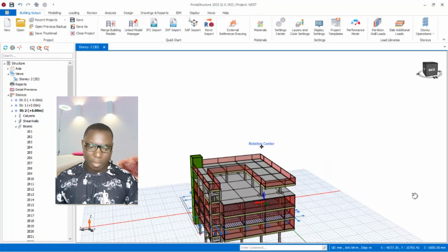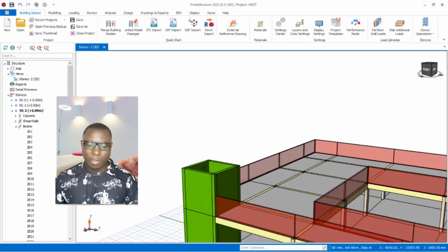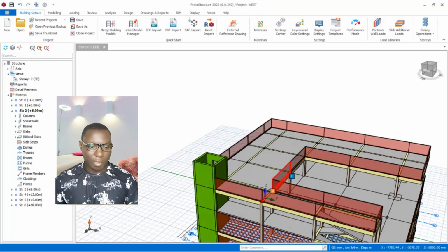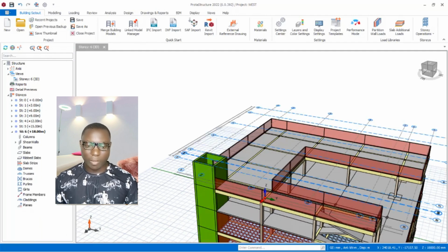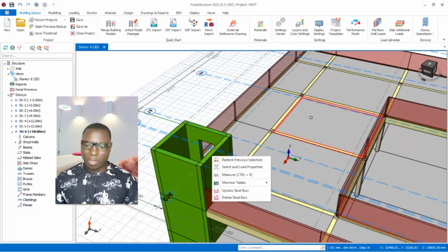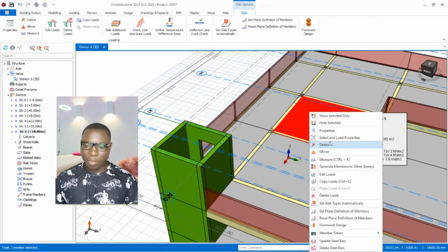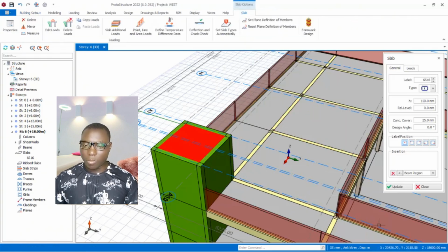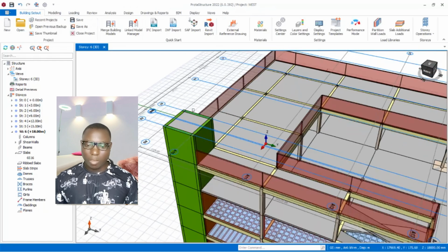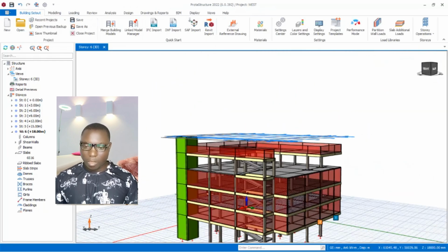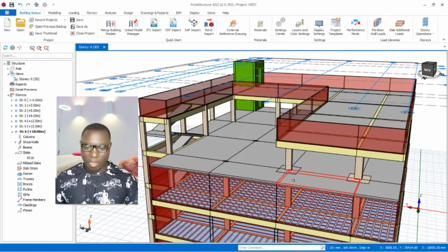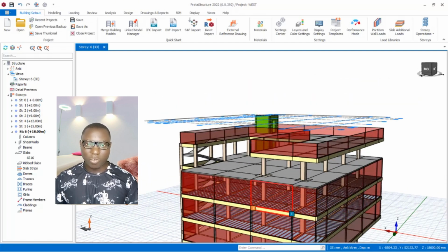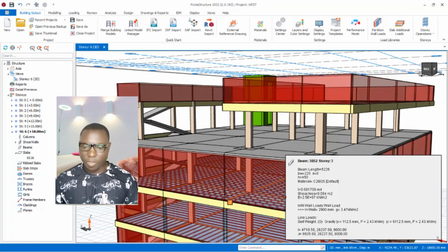All right, then for the top of the lift well, we are going to close it right here. So I will now double click on the Storey 6 to have it there. I can select any of these slabs, and then I click on the properties and use the property here successfully, just like this. I click on close options. You can see over here we have drops. As I said earlier, we have a drop in all of these provisions, and I've used this tool to show you how you can apply drops on the top of your columns successfully.